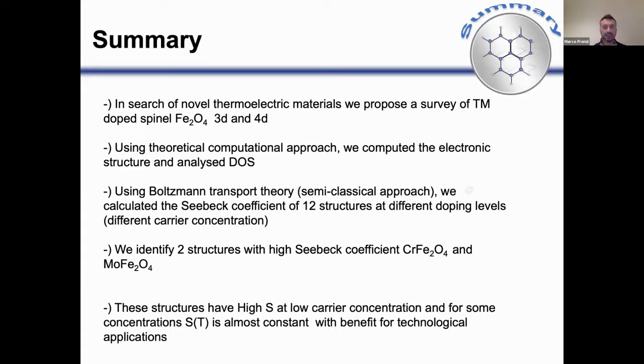We identified that these structures have high Seebeck coefficient and low carrier concentration. And for some concentrations, the Seebeck coefficient is almost constant, which is beneficial for thermoelectric practical applications.